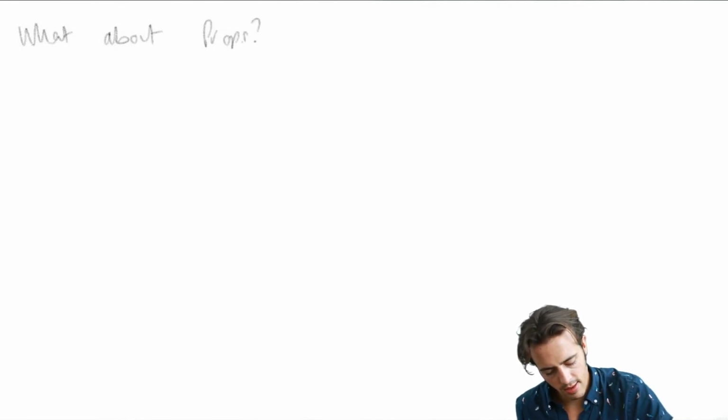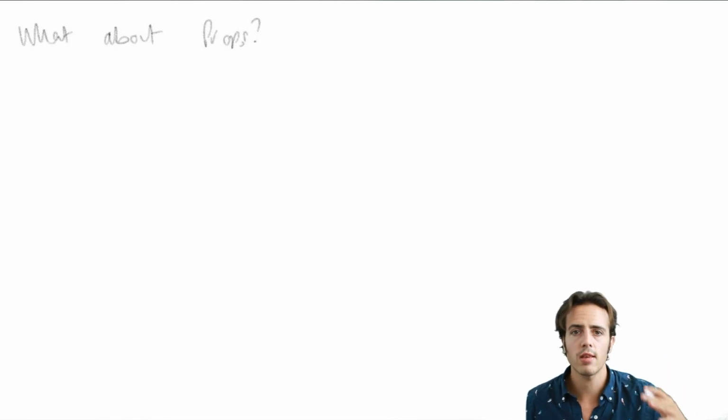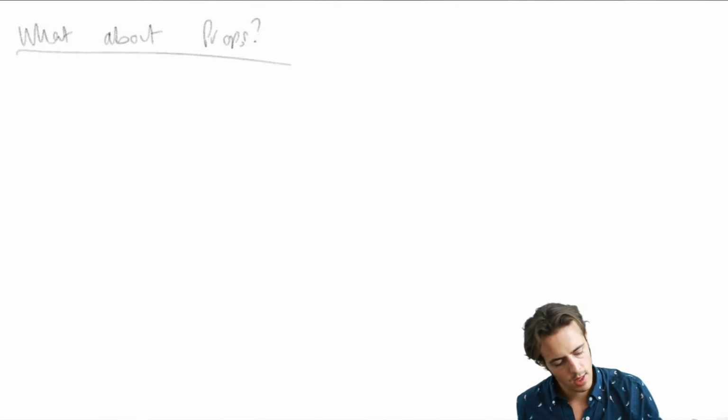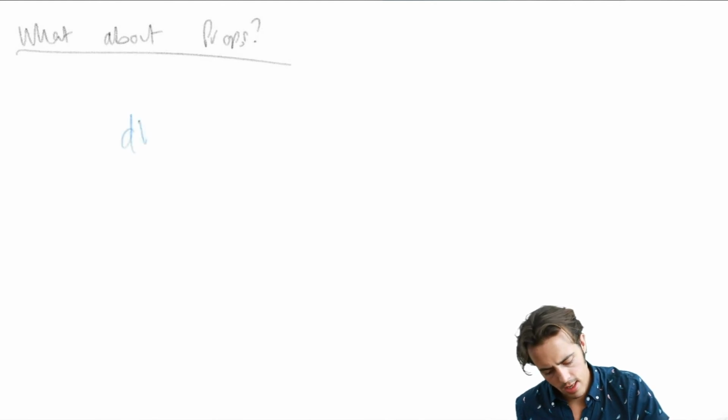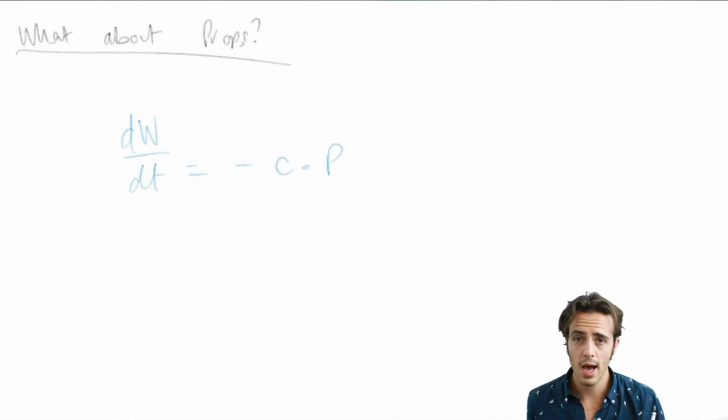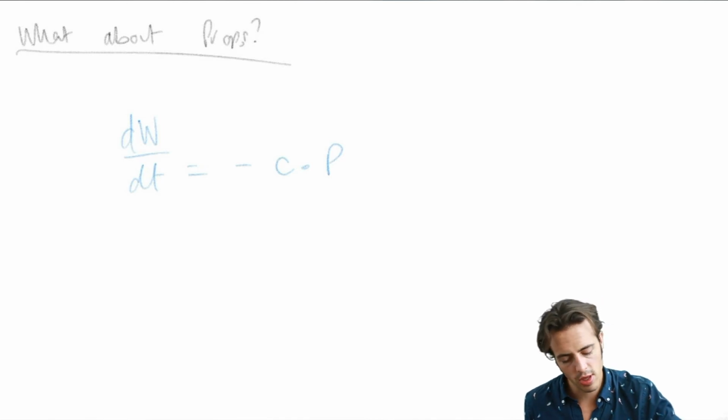So we have the exact same starting condition, which is the rate at which the aircraft weight is reduced is equal to the rate at which the weight of fuel is burned. So our starting point is again dW/dt is equal to minus the specific fuel consumption, multiplied by the power being produced by the engine, and then multiplied by g again. So we've got to be careful here.